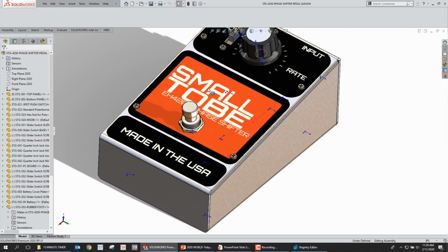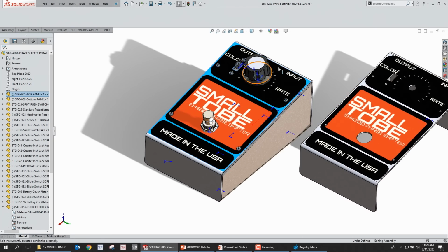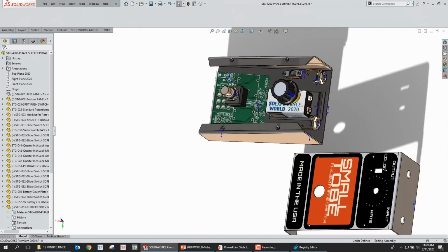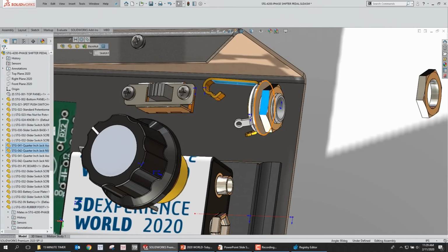All right, so with this, I can hold control and drag and make a copy of this part. So hold control and drag, make a copy. So if you've got a group of parts that you want to use in another spot, you could pick that group of parts and then just do control drag to copy them. So take this guy and this guy.